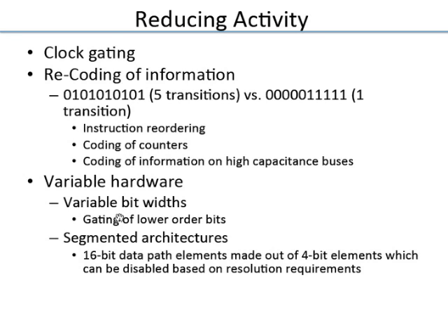So, for example, you have an 8-bit bus or a 16-bit bus. Maybe it is an application like a filter, right? You're doing a filter, and you decide that, look, I don't need a 16-bit word length. Maybe I can use an 8-bit word length for certain kinds of things. So you can then put zeros in the other 8 bits. So now you have no activity in those 8 bits, so you have reduced the activity factor. Again, it's a very application-specific example.